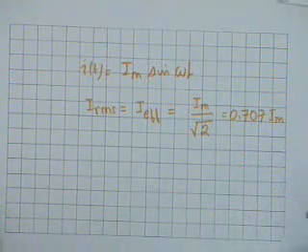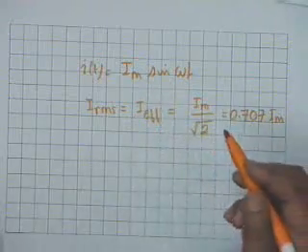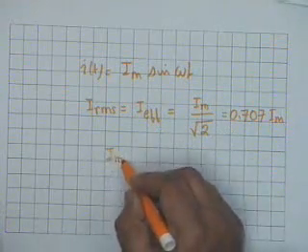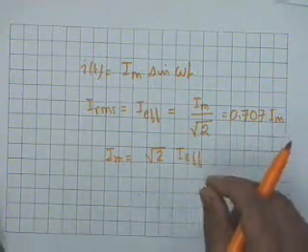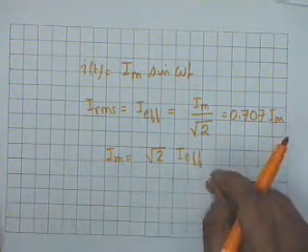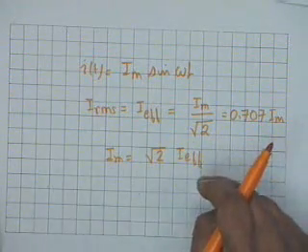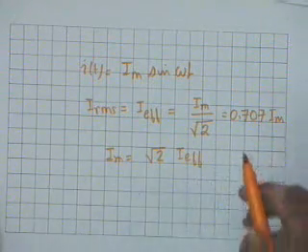All right. In other words, if the effective value is I effective, then the peak value is square root 2 times I effective, and when you say 230 volt AC, we mean the RMS value of the AC. So if you take a CRO and connect it to the mains power supply, then the maximum value you can measure will be 230 times root 2. This is true, I warn you, only for sinusoids.